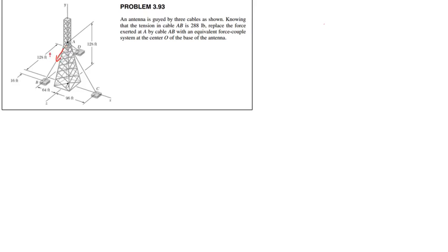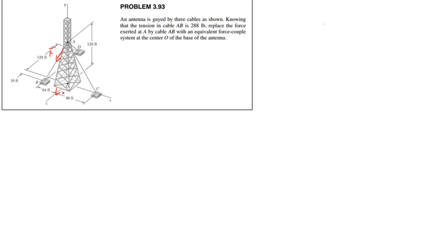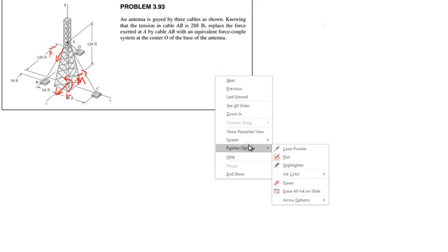And this is our F. So what we want to do is move this down to the origin. So we're going to have a force here, the same magnitude and direction as this F, same F. But we're also going to have some sort of moment vector, and we'll find that. That moment vector is simply going to be R cross F.